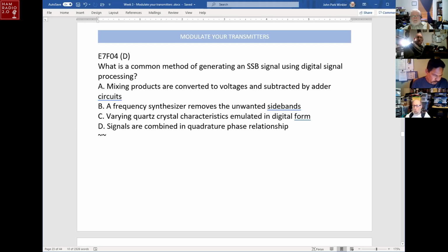And I saw a really inexpensive, I think it ran about $60, single sideband transmitter kit online that used a Class E amplifier, which we'll talk about in amplifiers, and a divided down set of digital signals so that they could produce the 90 degree separation, the quadrature phase relationship in the carrier in order to be able to receive single sideband.